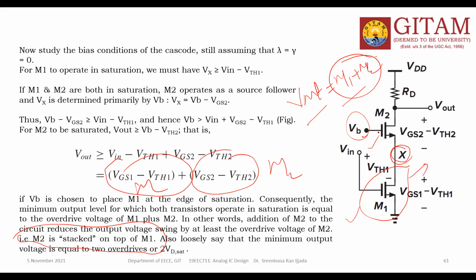For example, one transistor is there. This is my one transistor. This transistor should be replaced with two transistors which are connected in the cascode configuration like this. This is called the stacking operation. What can you achieve from this?